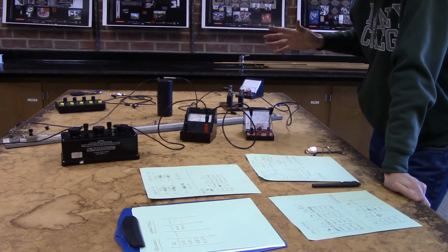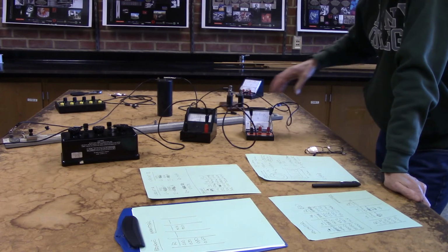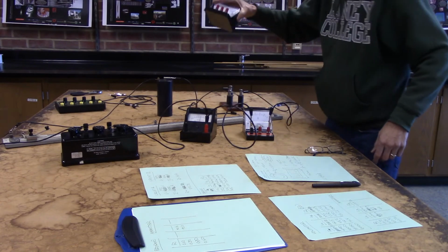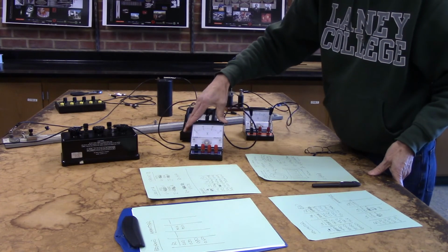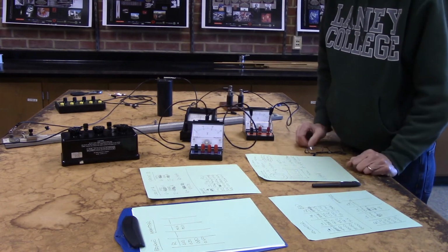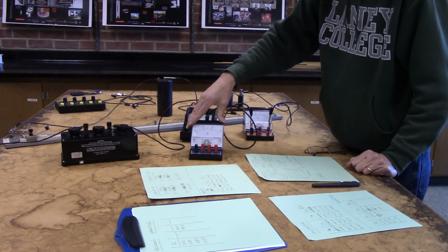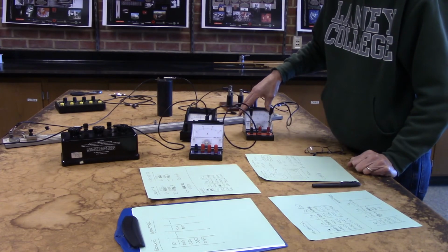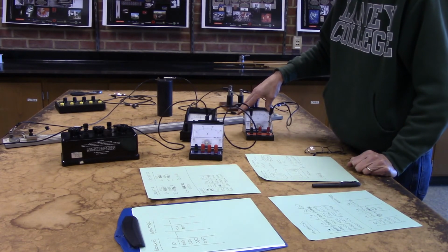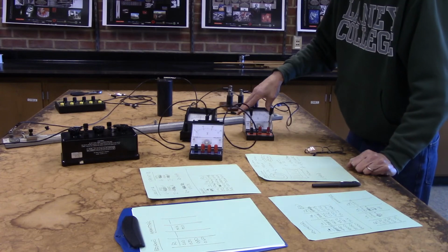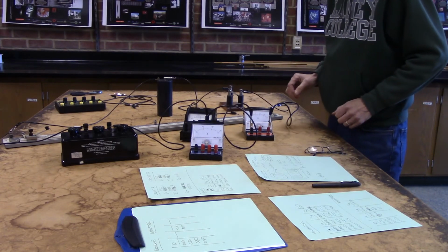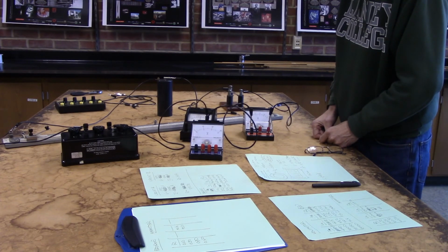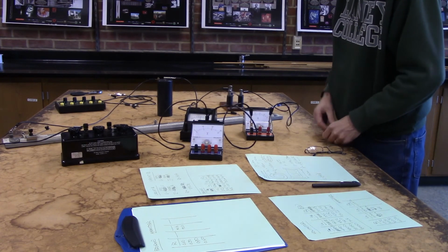So we're getting somewhere around 1/10 of an ohm for the ammeter, whereas with the voltmeter, we were getting thousands of ohms. So kind of what we talked about at the beginning of all this is that the voltmeters are designed to have lots and lots of resistance, and the ammeters are designed to have very little resistance to them. All right, so that takes care of our bridge measurements.